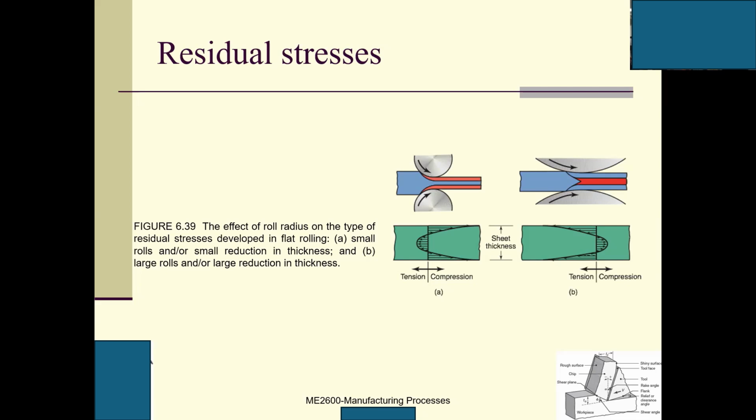Because you press it, there is an internal force to prevent the crack from initiating and propagating. Tensile residual stress is bad because tensile residual stress always facilitates crack initiation and crack propagation.